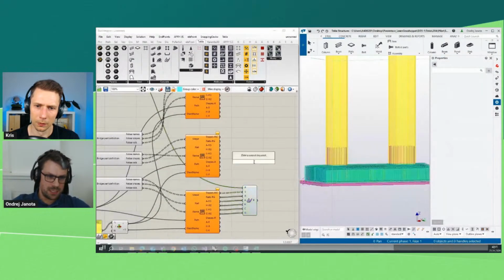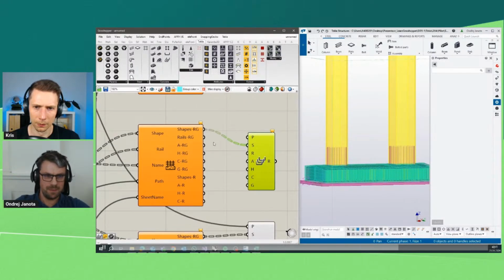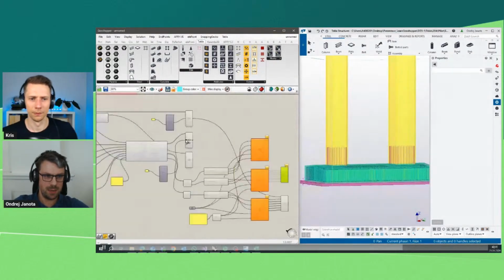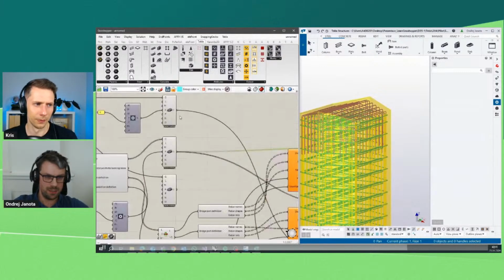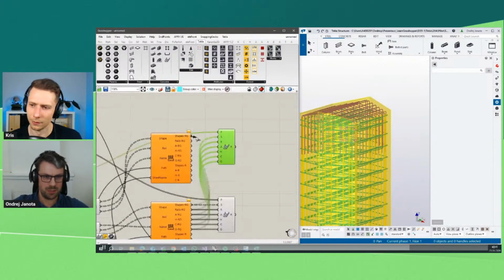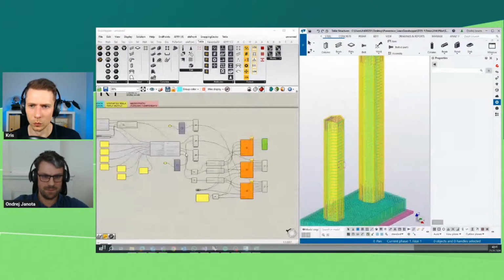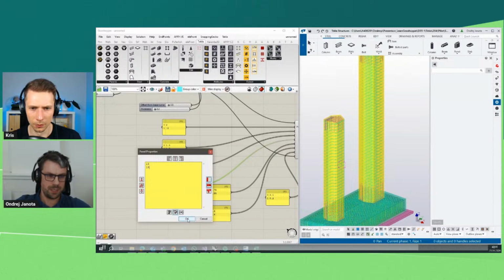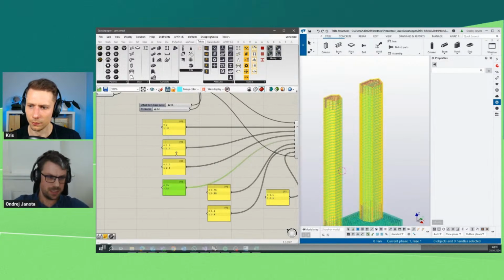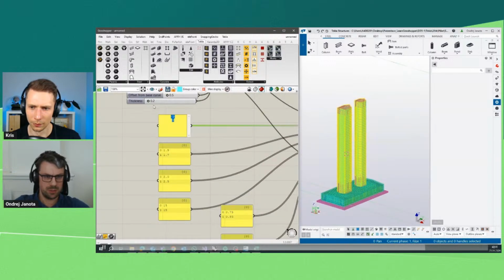And what I think is very important is that if you work on more and more projects, you are simply creating a library of your reinforced structures, and you can copy the reinforcement from one project to another. So if you have a different shape of the column on your pier, you define all the geometry once, and then you reuse it or use the Excel.